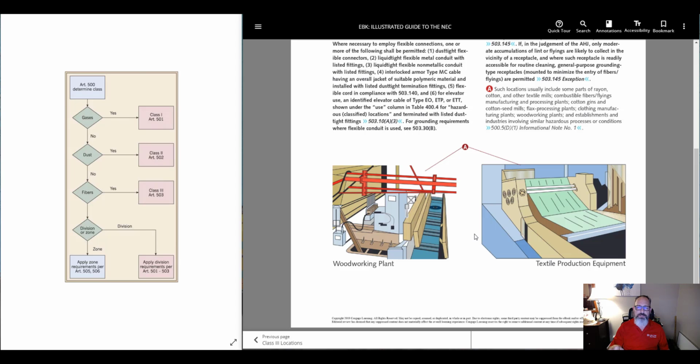So when you have these environments, you have a preventative maintenance situation that you have to stay on and make sure that the equipment is cleaned out. Shutting the manufacturing lines down, vacuuming out all the nooks and crannies and crevices, making sure that it's all clean so that you don't have a problem with combustibles getting stuck in the niches of the equipment.